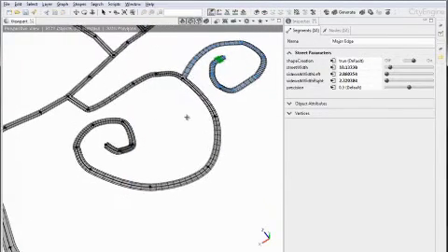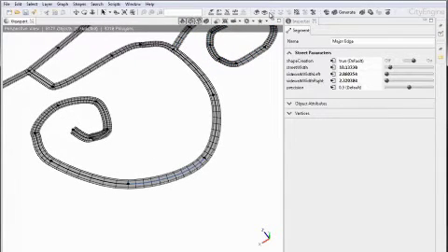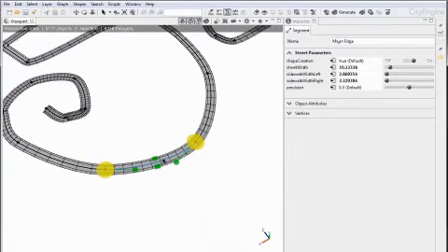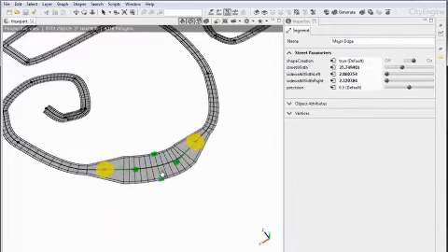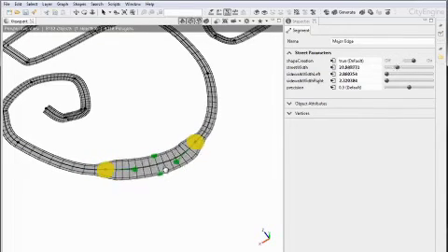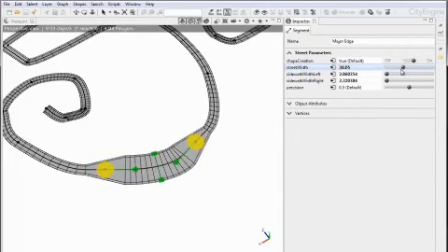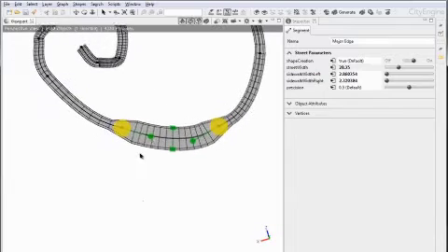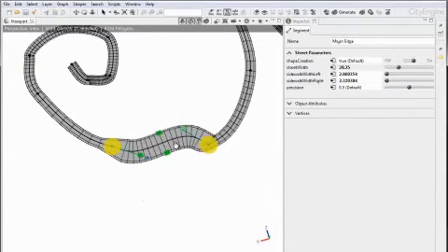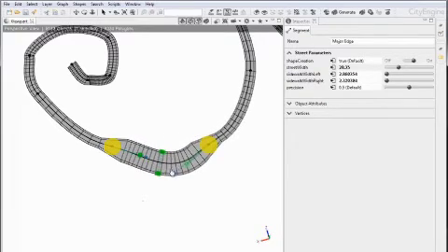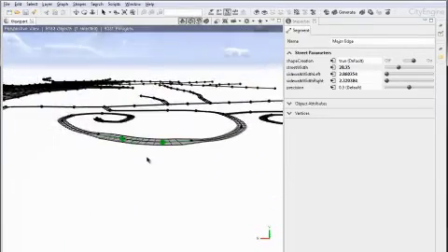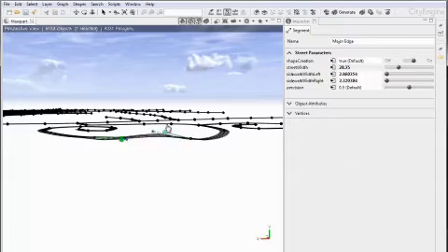So let's talk a little bit about the other tool, which is found here by the way, the Edit Street tool. You can also hit the C key on the keyboard. So let's do that. Now the Edit Street tool lets you edit multiple things within the same interface with handles. So you can go in and interactively edit the height, the width of the street, for example, and you see that it is the same parameter as in the inspector, but it is maybe a little bit more intuitive. So you can also go in and edit the horizontal handles when you look down, and if you're looking at a more glancing angle you can also edit the vertical tangents.